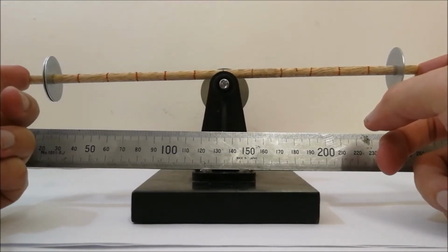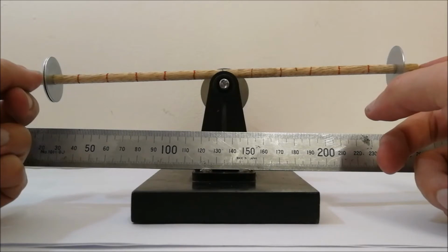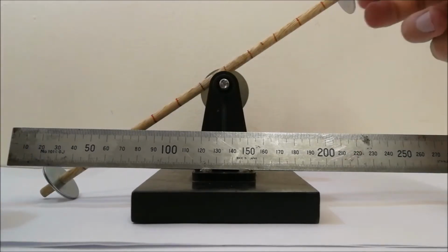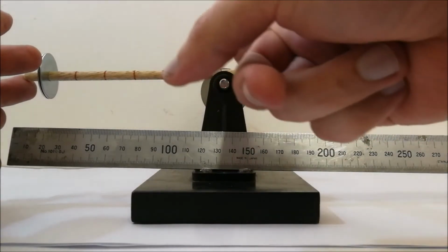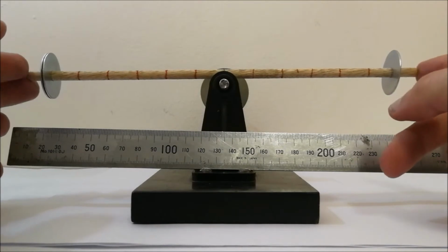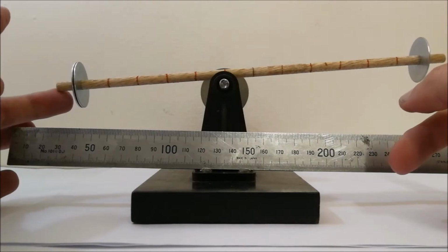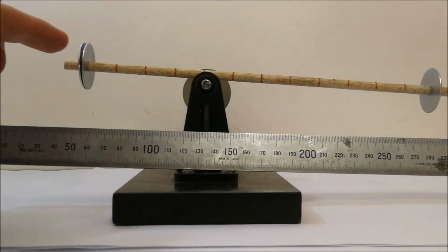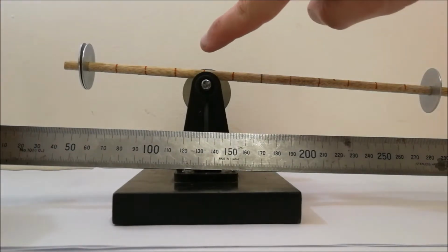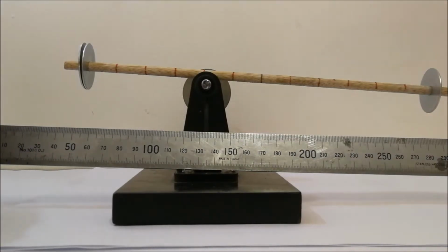Let's look at the first scenario. So I've placed on the left hand side 2 washers, and on the right hand side there's 1 washer. So at the moment it's wanting to tip to the left hand side. So where would I have to place this dowel stick, at least on this pivot point, to make it balance? Well, if I move it across a little bit over there, 20 millimeters, it's still wanting to tilt towards the left. The center pivot point is away from this specific washer 1, 2, 3, 4 segments of 20 millimeters, so it's away 80 millimeters.